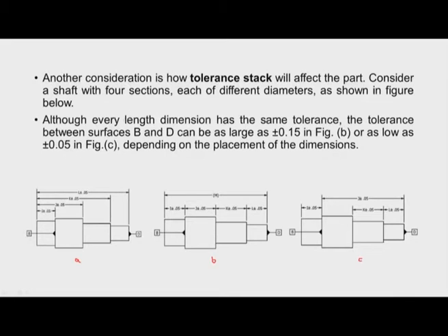Now another consideration while specifying the tolerance is the tolerance stack. The design engineer should understand the effect of this tolerance stack. We can see here three pictures with four circular features with varying diameters and varying lengths with some tolerances.